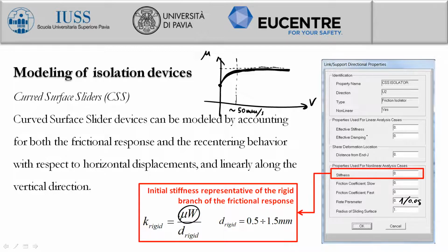I was thinking about how we can account for the P-Delta effects that are transmitted by the device to the superstructure, this additional force related to the displacement of the isolator. I don't know, as a couple of bending moments, or an additional shear couple. What's the difference? What is the best and most efficient way to account for this effect?